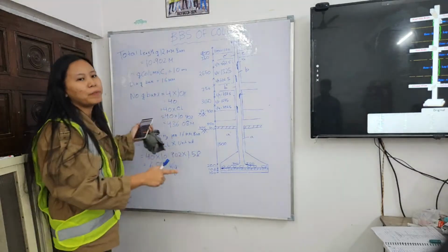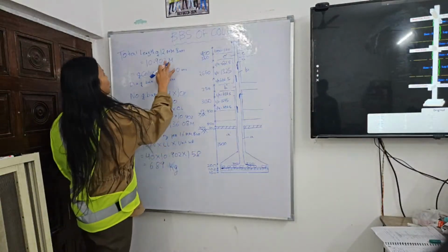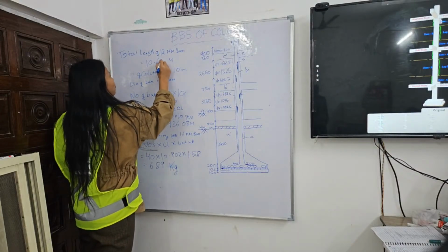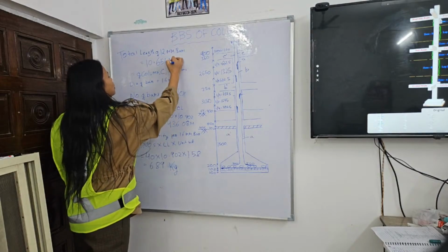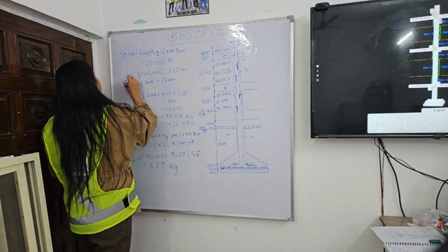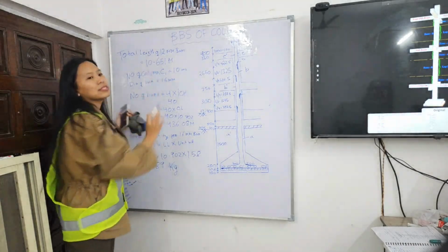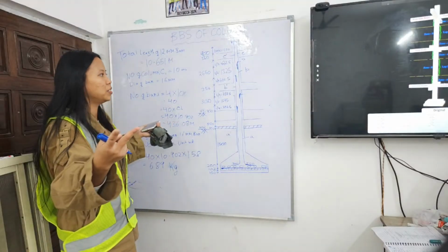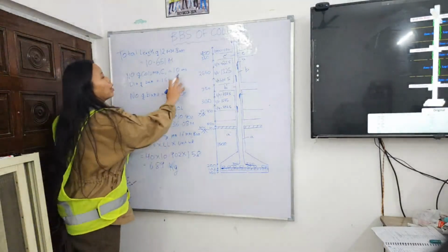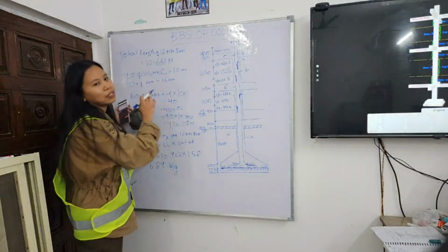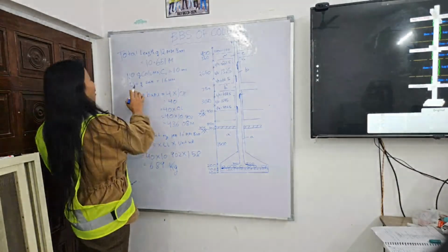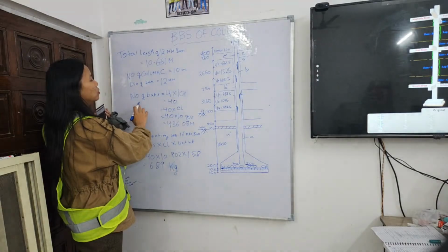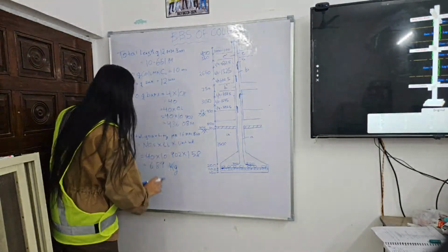Total length of 12 mm bar I've calculated from before, which will be 10.651 meter. And then most of the column, the same thing, because we're going to be making the same column using the two bars, which is 16 mm and 12 mm. So we have 10 columns, C1, and the diameter of the bar is 12. Now the number of the bars, they are the same thing.